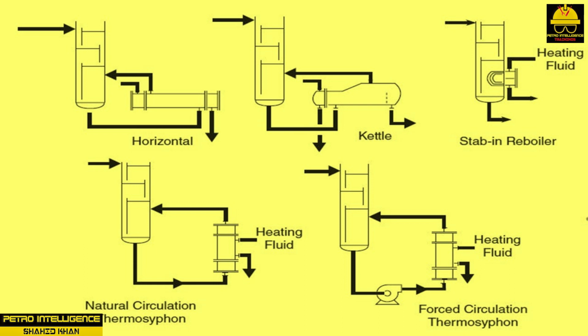A vapor inlet port is located below the bottom tray or packing support. An important criterion for a distillation column is that any heat energy lost must be returned. Reboilers are used to restore heat balance and add additional heat for the separation processes.